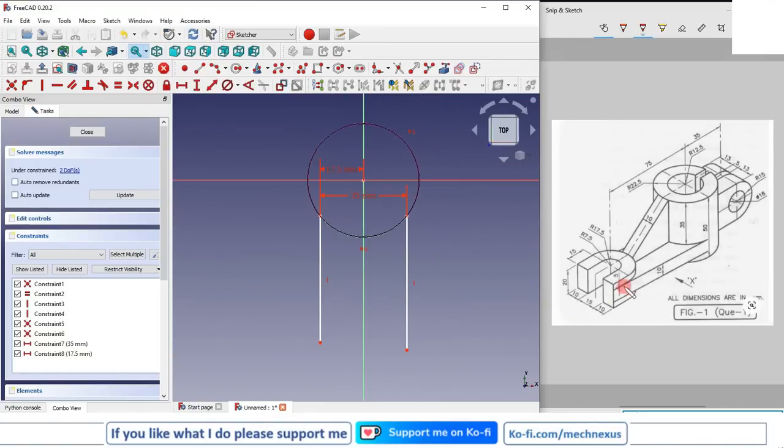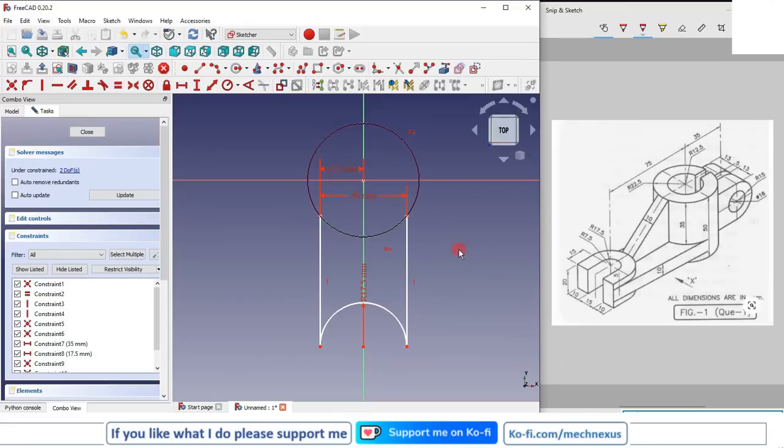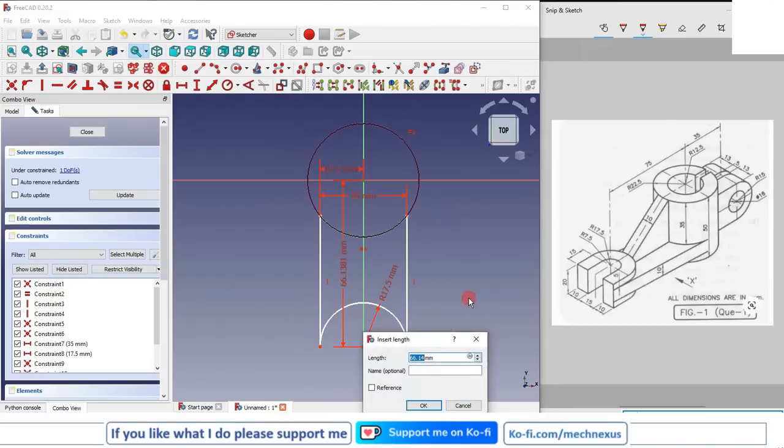Now we will create this arc here, which is of R17.5. So again I will select the 3-point arc, and I will give the radius, which is 17.5, and center to center distance is a 75, so I will move it and I will give it dimension of 75.